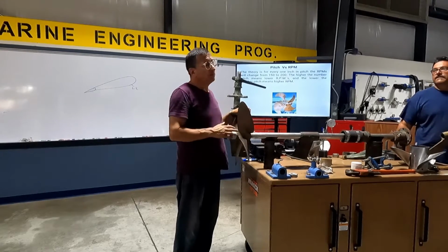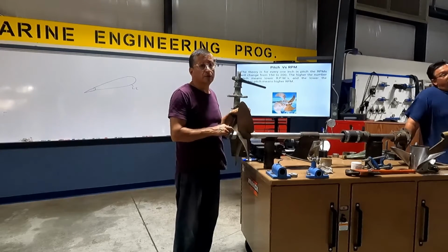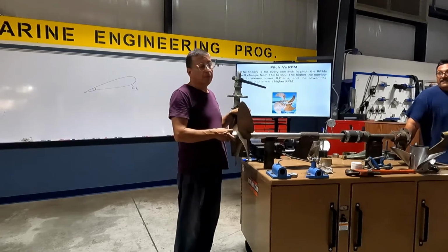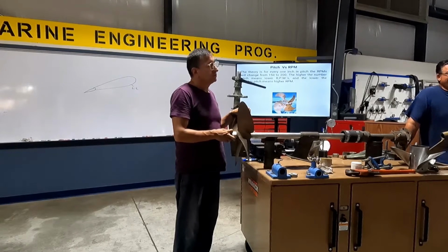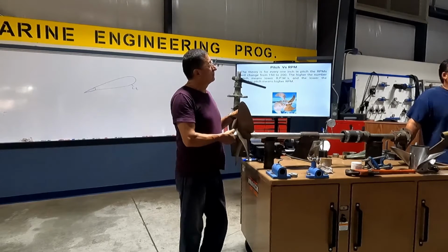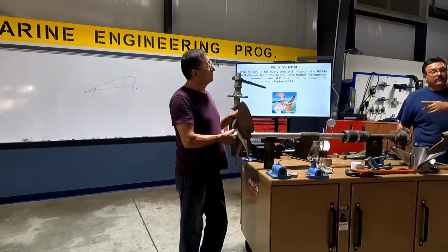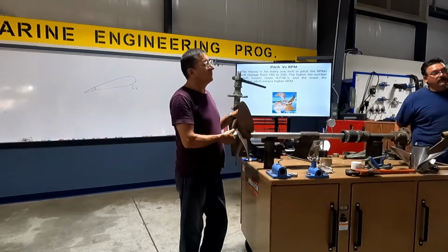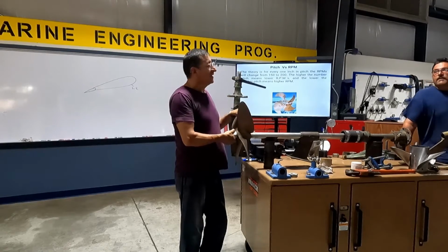However, the procedure to replace the propeller is simple in outboards in comparison with inboards. You need a diver in some cases to replace the propeller, especially if it's a 40 by 52. As soon as you pull it out, it's going to go right to the bottom. You need a buoy and ropes. Yeah, you could change an outboard prop or even a stern drive prop or a small inboard prop like that in the water. It's a pain, but you can do it. But not one of those big props. I have a good video about the replacement of that propeller in the water.